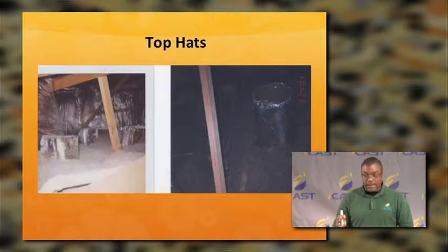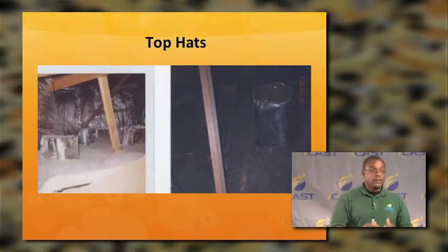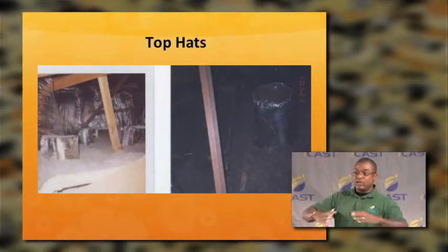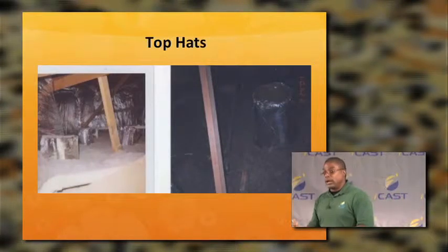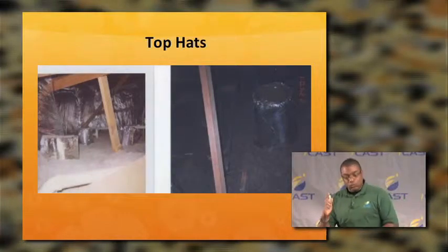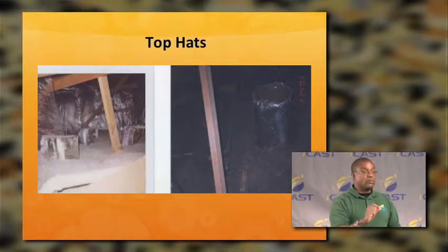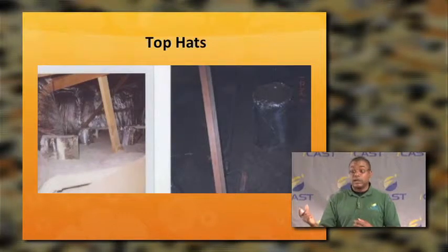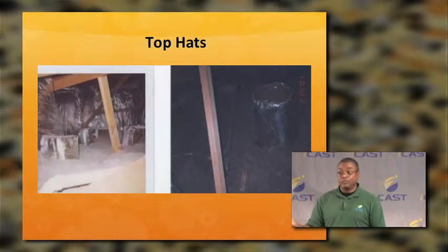The nice thing about top hats is that even if you're burning a high-watt bulb, there's enough air around that can light to allow that heat to continue to dissipate without losing the air, so you don't end up burning up your can light or overheating your light bulb. One of the things that you can do, though, is recommend that your homeowners use CFLs instead of an incandescent light bulb, because CFLs generate less heat than the incandescent light bulb.